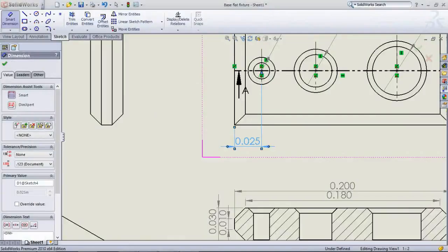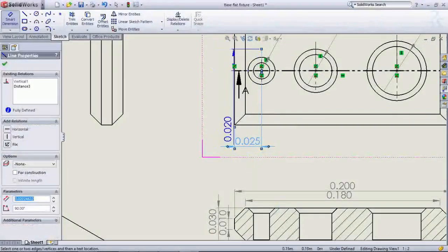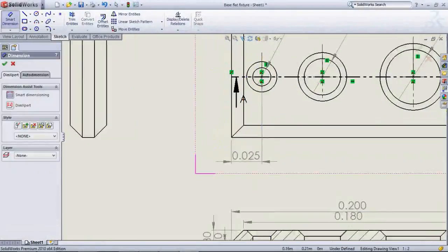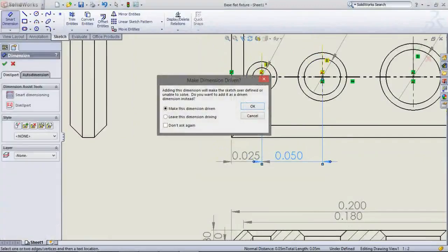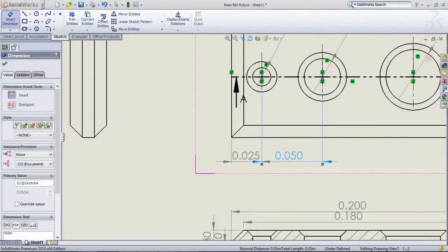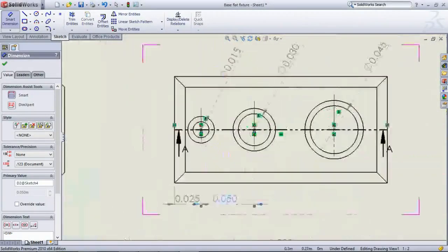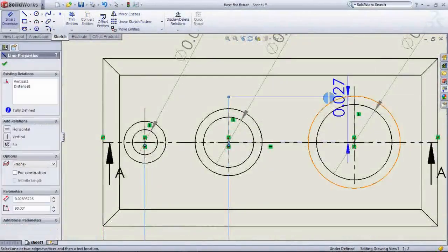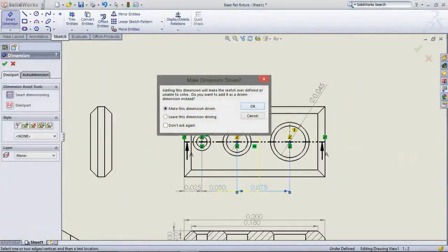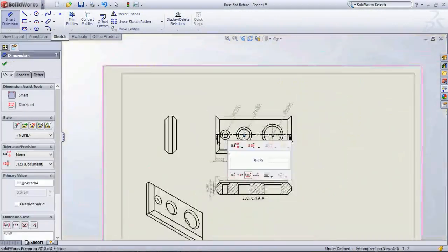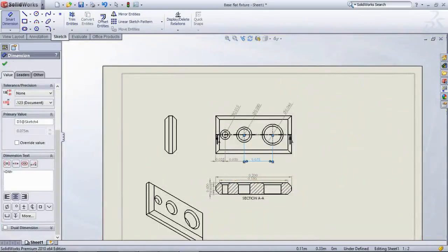For drilling, he will first mark the center point of those holes. For the center point of the hole, he will understand the coordinate by considering the lower left bottom corner as 0,0, and then the coordinate of the center point of each and every hole.